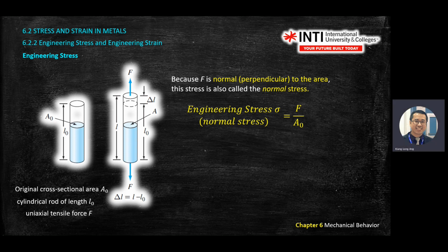I'm going to highlight another area. This top area will give you shear stress. Same symbol, but you have a shear subscript there. Why is this one shear? Because the red arrow is parallel to the cross-section area. Or if I drop the cross-section area here, parallel to the force, I still get this area.